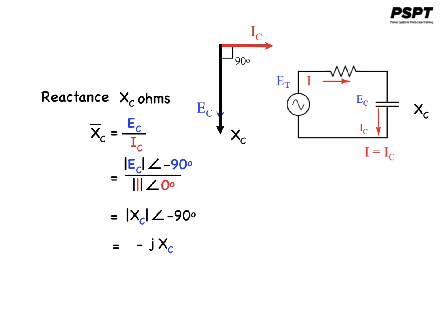Since capacitors conduct current in proportion to the rate of change of the voltage, they will pass more current for faster changing voltages and less current for slower changing voltages. What this means is that reactance in ohms for any capacitor is inversely proportional to the frequency of the alternating current, and notably also inversely proportional to the capacitance of the capacitor.